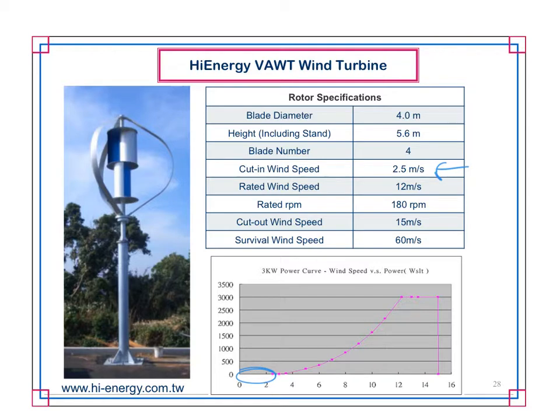Look at the RPM here, much higher RPM, right? The other one was, what was it, 14.8? This is 180, so 10 times greater. If the power in the wind is too great, we already talked about this, there isn't enough induced torque provided from the generator to slow the unit down as it continues to do that. So at that point, you are having so much power that you can't maintain a safe system.